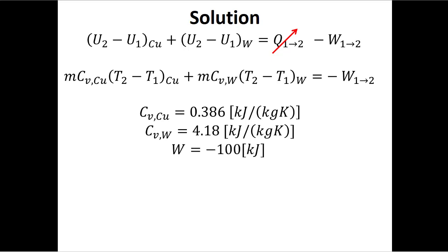The trickier part is the work. This energy that's coming in electrically could be used to move something, to apply a force over a distance. So we can think about this as work if we want. This is energy coming into our system, so if we think about this as work, then this would be work in to our system, and work in is negative.